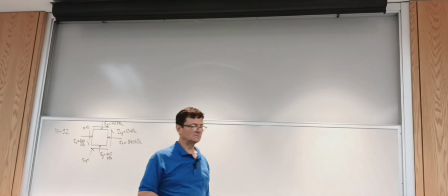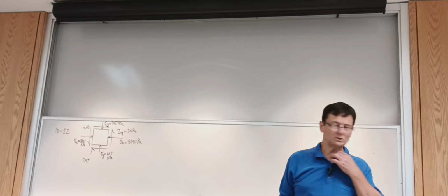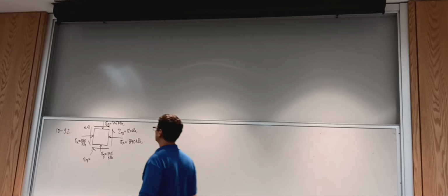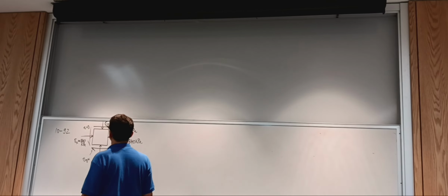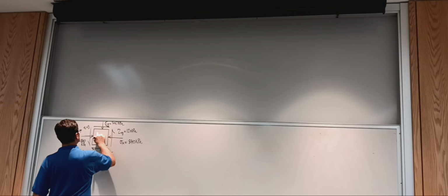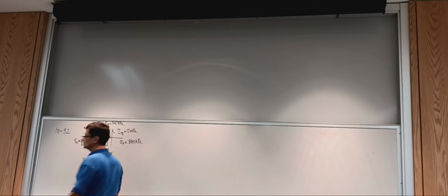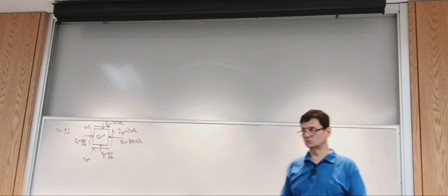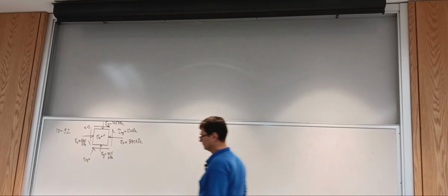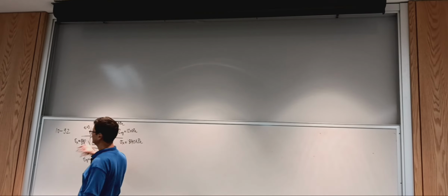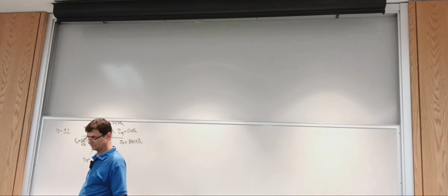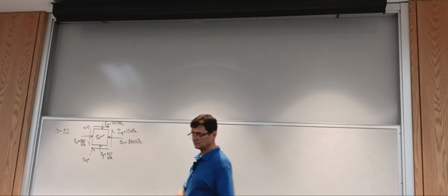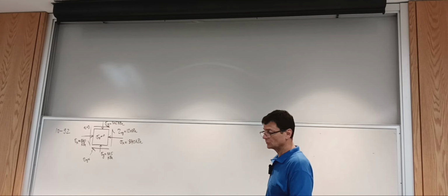Their orientation is based on the direction in which they tend to rotate the element. Then we have sigma z, which is 0. That's the ambient pressure. It might not be 0 as a rule; the whole thing can be subject to hydrostatic pressure.